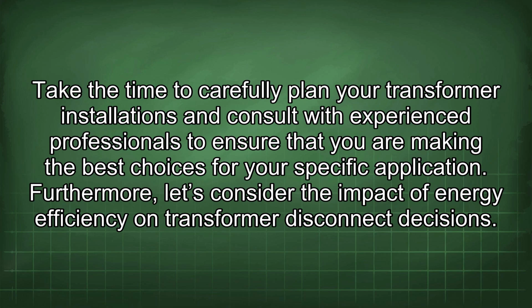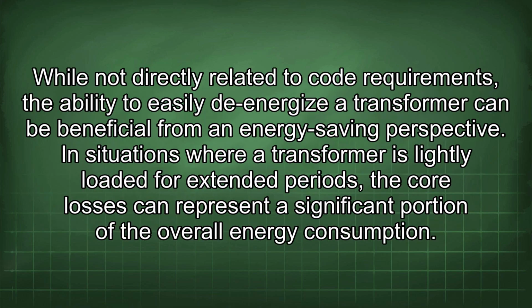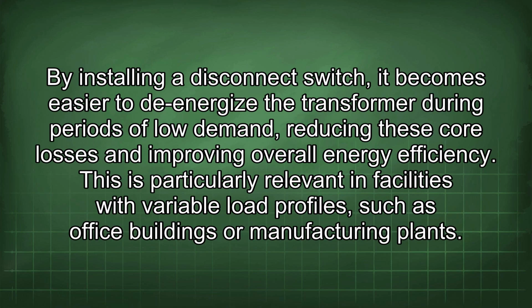Furthermore, let's consider the impact of energy efficiency on transformer disconnect decisions. While not directly related to code requirements, the ability to easily de-energize a transformer can be beneficial from an energy-saving perspective. In situations where a transformer is lightly loaded for extended periods, the core losses can represent a significant portion of the overall energy consumption. By installing a disconnect switch, it becomes easier to de-energize the transformer during periods of low demand, reducing these core losses and improving overall energy efficiency. This is particularly relevant in facilities with variable load profiles, such as office buildings or manufacturing plants.